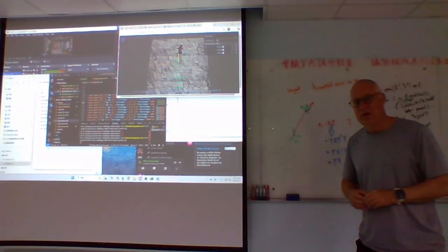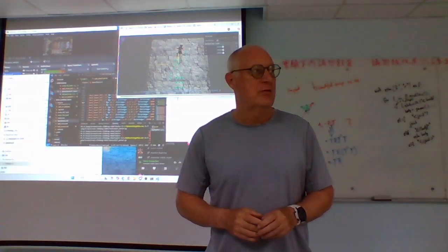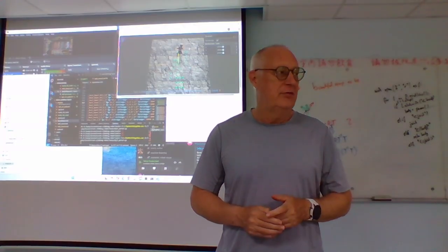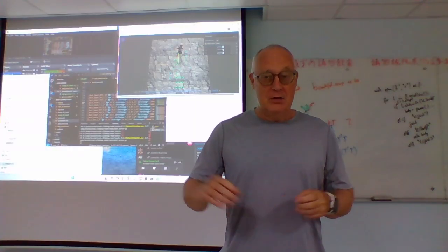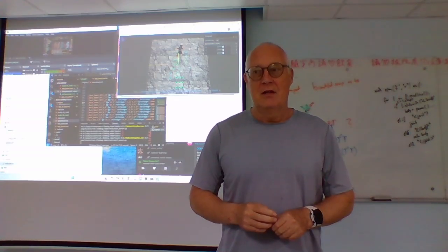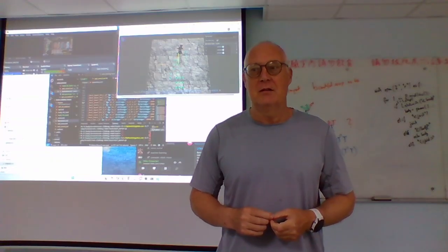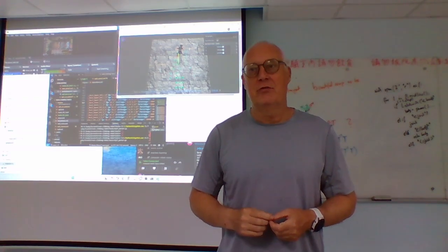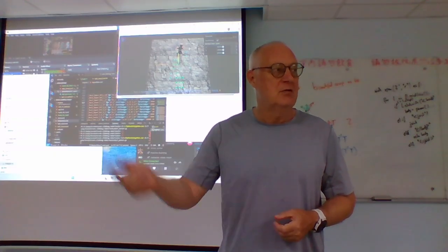Once we have the forward kinematics, calculating the inverse kinematics using the Jacobian approximation is also not too bad. You take your current state, calculate the forward kinematics, then change each one of the joints by a tiny little bit, see how much your x, y, and z position changes, and then take a step in that direction.